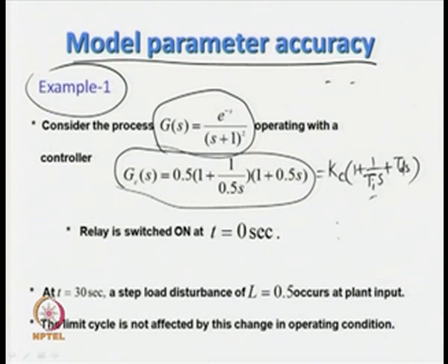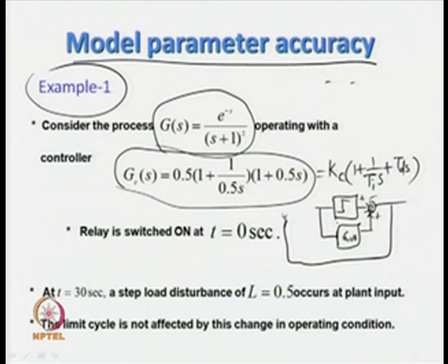Now, when the controller and relay are connected in parallel, and the relay is a symmetrical relay, then a limit cycle is induced, or sustained oscillatory output is obtained.